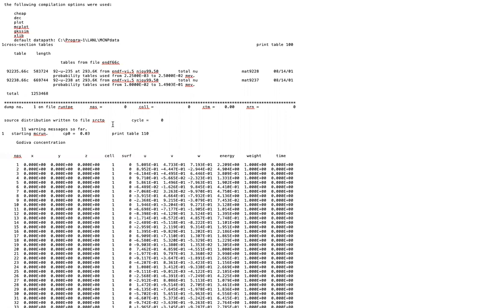And so it tells you now run tape. In our days, we actually used to have tapes. But you don't now see the tape, it's your laptop actually. So the first dump it's going to do on RUNTPE, the next on RUNTPF, then G, and so on. So the simulation begins.